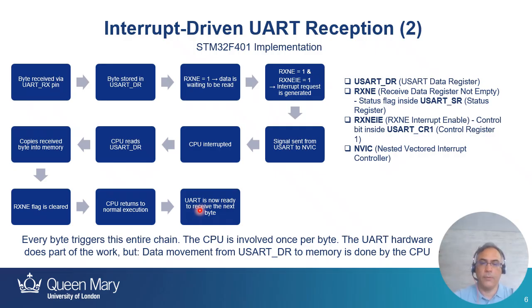So every byte triggers an entire chain. The CPU is involved once per byte. The UART hardware does part of the work, but data movement from the USART data register to the memory is done by the CPU.